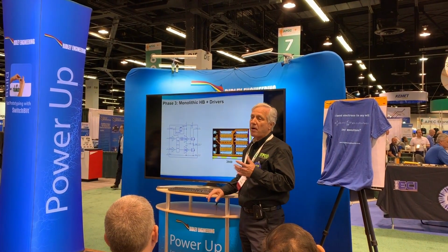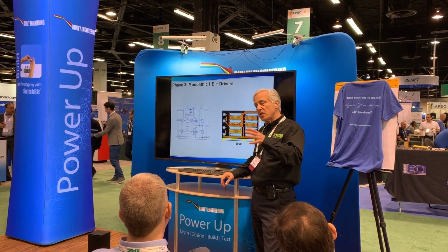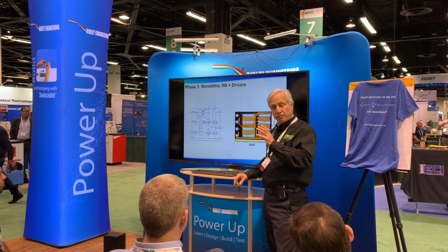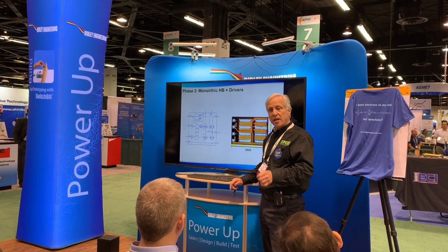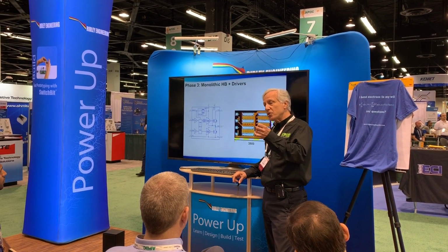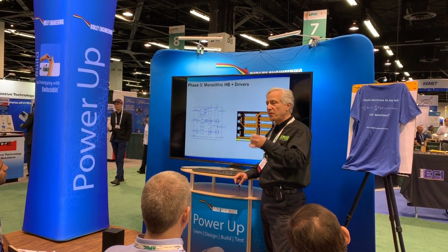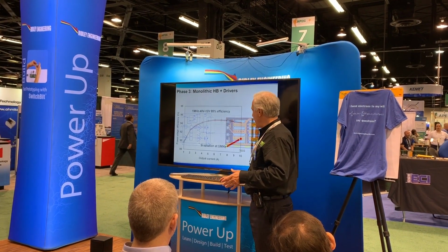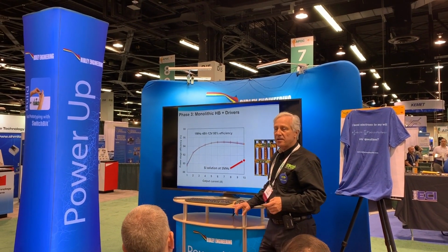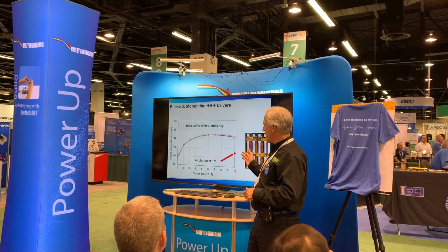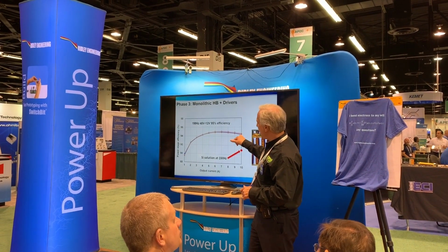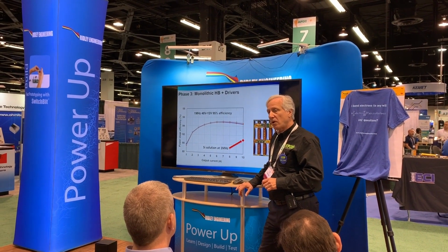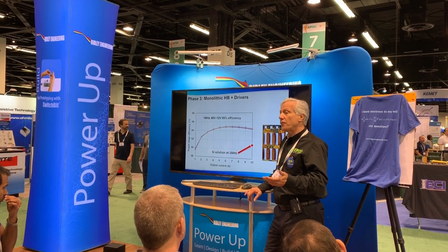It's a fully monolithic power stage. And I would contend that this is where power conversion is going for the future. This redefines what a component is. Discrete power transistors are only discrete power transistors because we couldn't figure out how to integrate them in silicon. We tried, and we tried, and we tried, and so nowadays you can in GaN, because GaN integrates multiple power devices very easily. This is showing you running at 10 amps, about 95% efficient at a megahertz. This is the closest silicon series, several points lower. So this is where the future is really going to go.